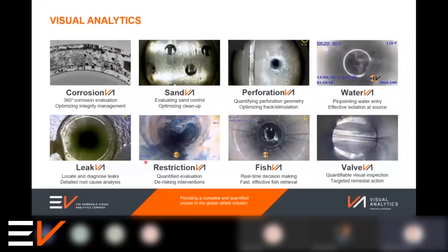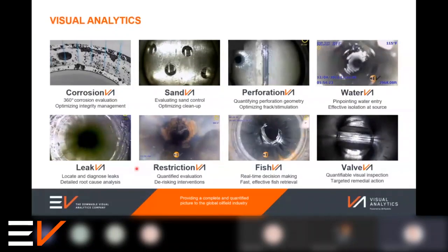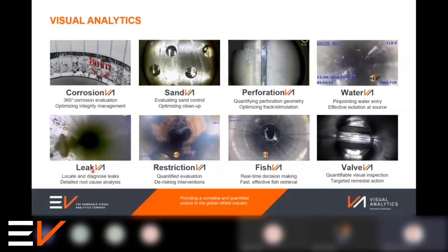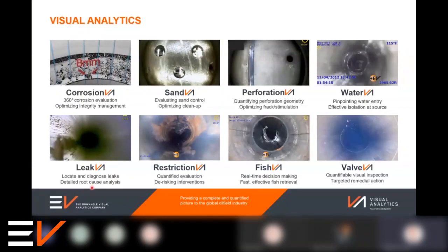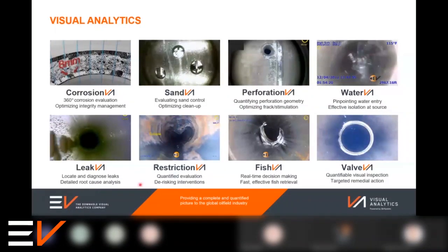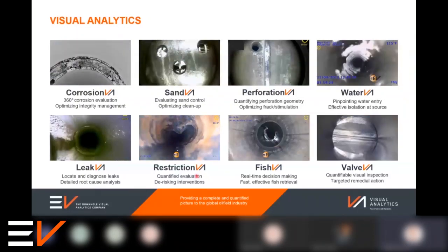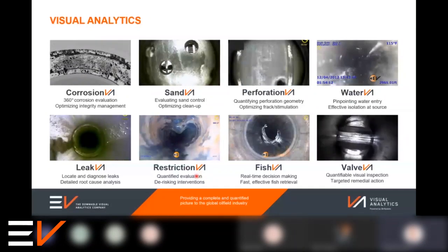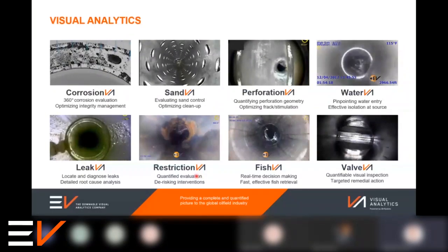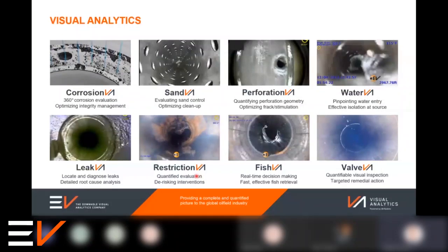Then on the second line, what you might consider to be more reactive diagnostic services to assist with immediate remediation. These might include the identification of leak sites and helping to understand what's caused them and what the surrounding area looks like to determine what course of remediation to take. We also do a large amount of work in understanding wellbore restrictions, not just straightforward obstructions or collapse like we see here, but even pipe deformation that we can then use multi-finger caliper combined with video to understand the limits of well entry to help you meet your objectives without compromising the job.